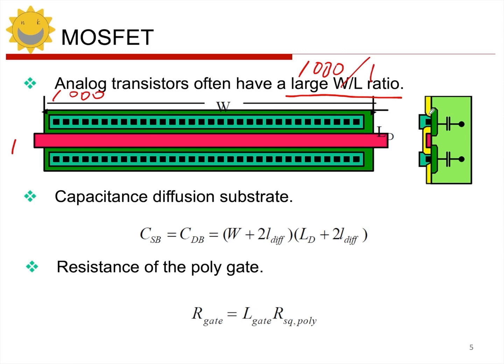What will a reverse bias PN junction have? Capacitance. So here, there will be a parasitic PN junction capacitance. Its size is related to the area of the source drain, right? The larger the area, the greater the capacitance. So if you draw a long transistor, then your source drain region will definitely be long and large, which means its body junction will also be quite big.